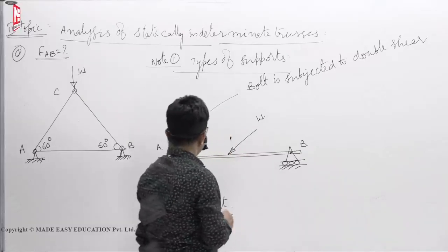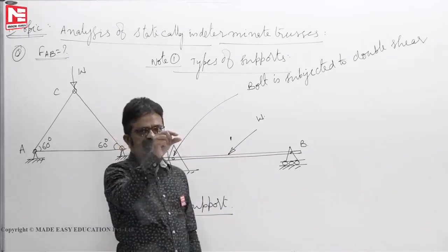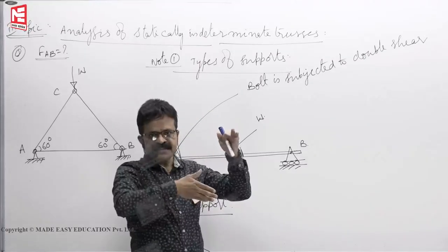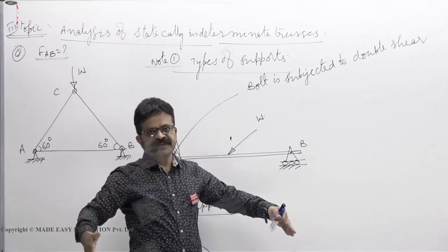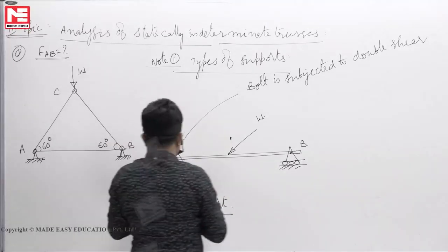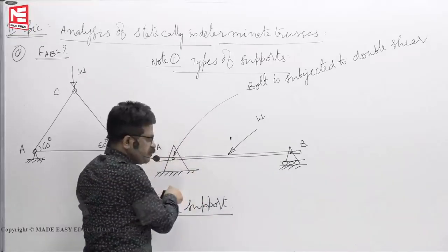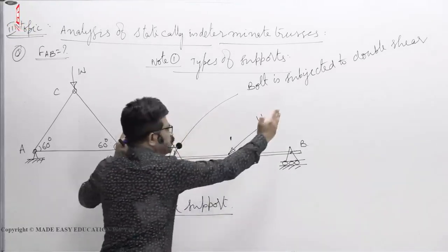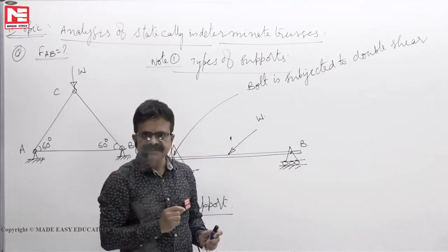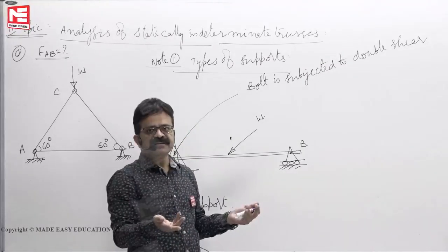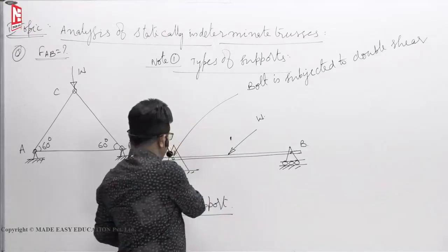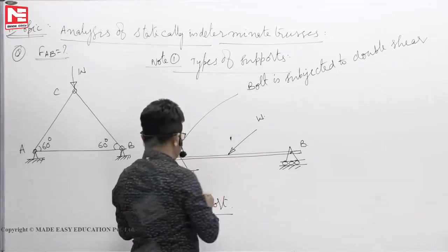Okay. Now similarly here, pin, when it is there, pin exerts like a point load. Effect of that point load on the steel, it is like a load dispersion line is 45 degrees line. So that's why you get a triangular shape. If you put a rectangular plate here, say, then that much of plate metal is simply wasted, because the effect is not there at all. So that's why if you put a triangular one, you are effectively utilizing the triangular plate front side, triangular plate back side.